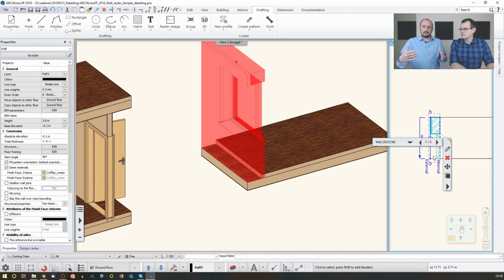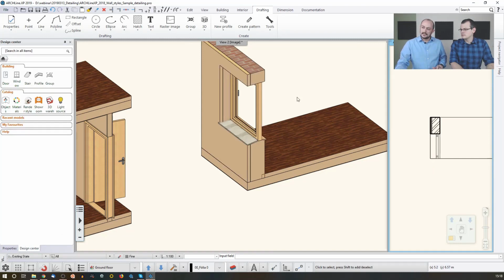And whenever I make changes, I should not make my building bigger than the expected size. So that's why I drew it like that, and that's where you can see the reference line. And whenever you add the layer, it will just move inwards, so you will lose space from the interior, which can be changed as well, I just really need to stress that.